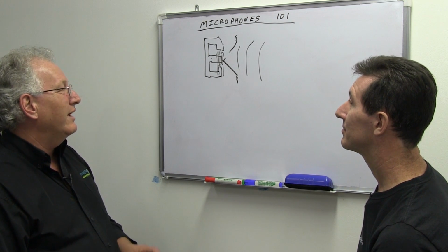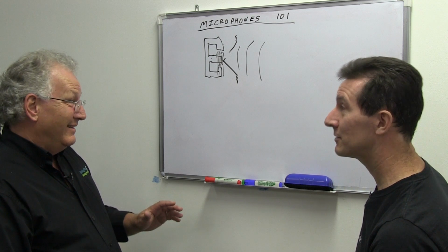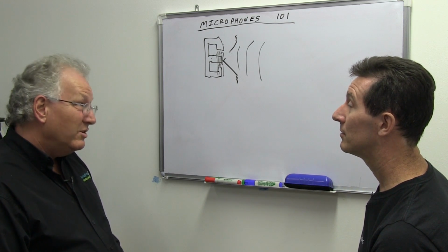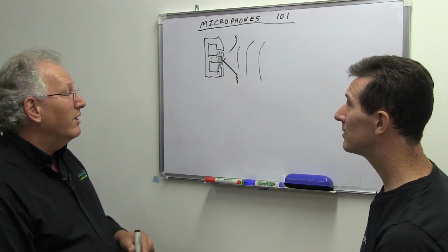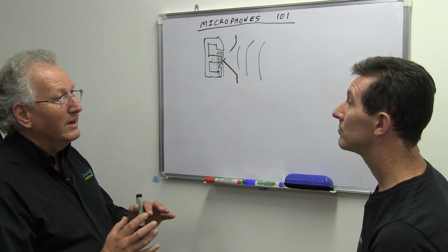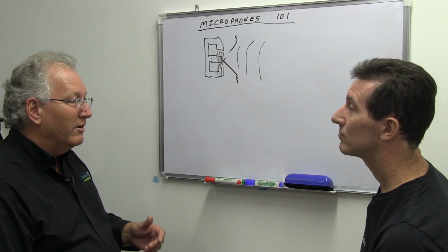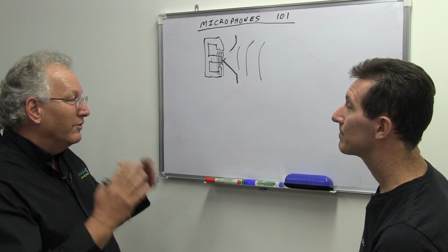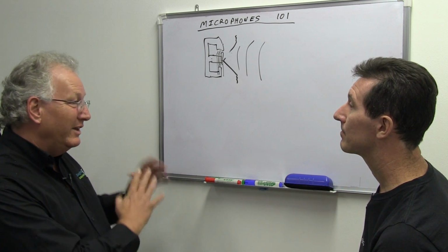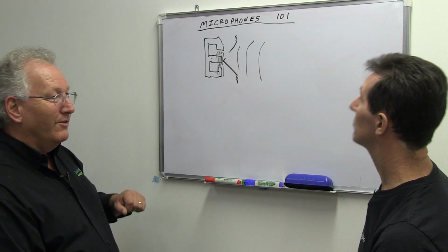Frequency response as a microphone is absolute rubbish. And they're probably insensitive as hell as well. They're actually relatively sensitive, despite the fact that they're a low impedance device. Their voltage sensitivity, you wouldn't write home about, but their ability to convert sound pressure into electrical energy is probably better than an actual microphone.